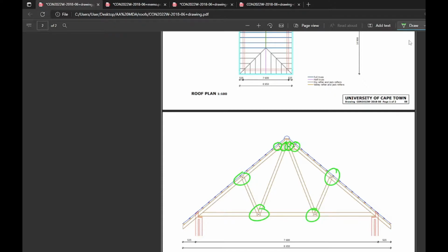There are types of bolts, M16 and M10, and that pertains to the thickness of the timber it has to travel through, right? So 100 mils plus is an M16, and I don't mean the weapon. And an M10, we will just assume it's less than 100 mils. That's because I'm being a bit lazy and not looking at the table. There is a table for these bolts. Let's just make things a little bit easier. So 100 mils or less is M10, and greater than 100 mils we'll say is M16.